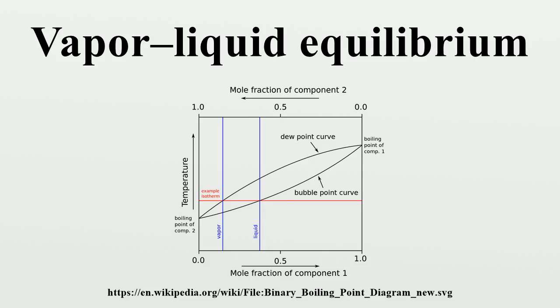If one wants to represent VLE data for a three-component mixture as a boiling point diagram, a three-dimensional graph can be used. Two of the dimensions would be used to represent the composition mole fractions, and the third dimension would be the temperature. Using 2 dimensions, the composition can be represented as an equilateral triangle in which each corner represents one of the pure components. The edges of the triangle represent a mixture of the two components at each end of the edge. Any point inside the triangle represents the composition of a mixture of all three components.